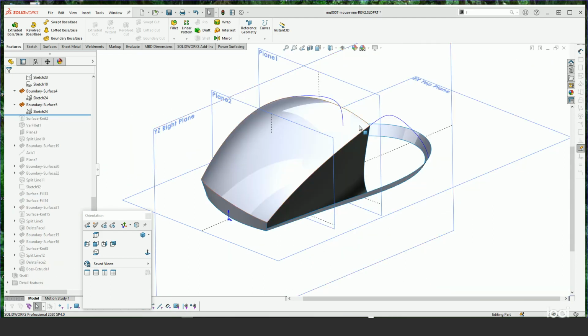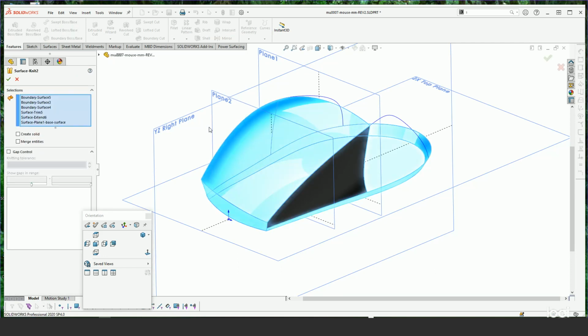Moving on, I'm going to now establish the radiuses that run along this left and right top edge. Before I do that, as a surface body, I need to knit all 3 of these together. So I've just very simply taken actually all of my surfaces and knit them together along with the bottom.